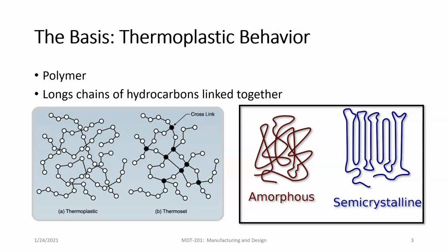And that's a good way to look at if you want to know whether an object is a thermoplastic or a thermoset: heat it up. If it melts and then you can reform it, then it's a thermoplastic. If you heat up a thermoset, it's going to burn.